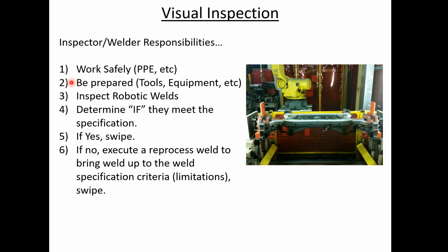Here's a great example. I went to a large plant many years ago, and I was actually conducting this particular audit, and I walked up to a fella, and I was being supervised by the plant. They were watching me, and I walked up to one of the reprocess guys, who was clearly, by the way, a very good reprocess welder. He could act quickly to inspect. He executed the weld, and he was very calm and did a good repair. But I asked him, I said, so if you see porosity, what do you do? And he said to me, he was properly trained, because he said to me, porosity that does not meet the specification requires grinding. And I said, that's a fantastic answer.